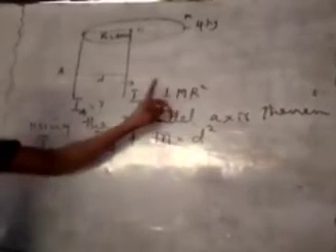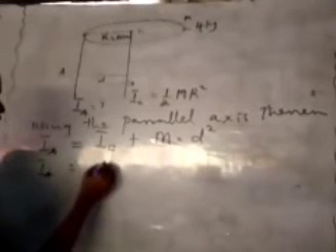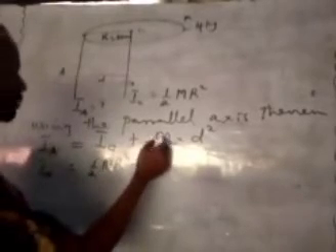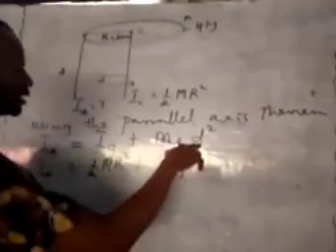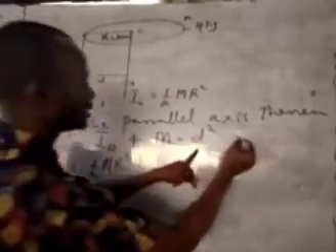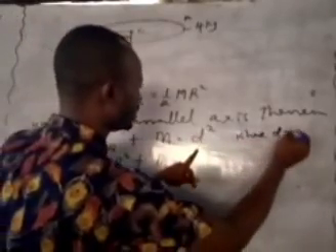So now watch. The inertia about the axis A will now be equal to, remember, the inertia about the center of gravity, which is half m r squared, plus the mass m times the distance of separation squared. Please take notes, where this d is the same thing as r.